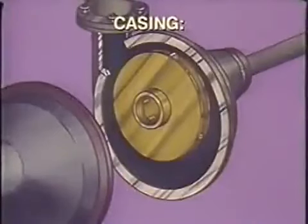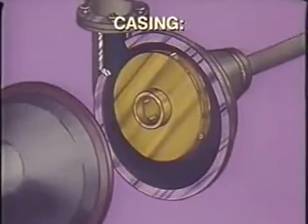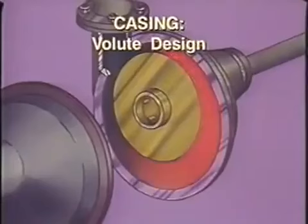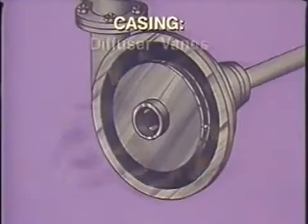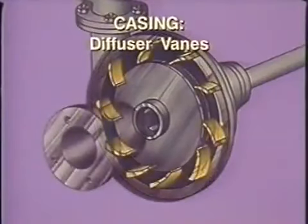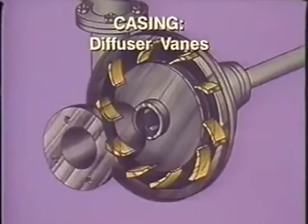Let's take a closer look at the parts of the pump. First, let's consider the casing. A function of the casing is to reduce the velocity energy of the liquid and convert it into higher pressure. The casing shown here uses a volute design to make this conversion. Another way to convert velocity into pressure is to place diffuser vanes in the casing which slow down the flow, causing the pressure to rise.